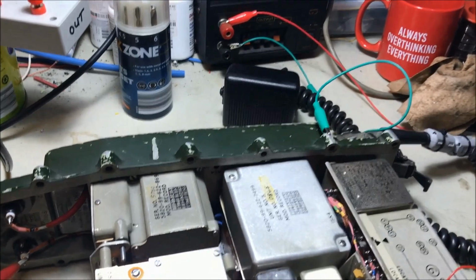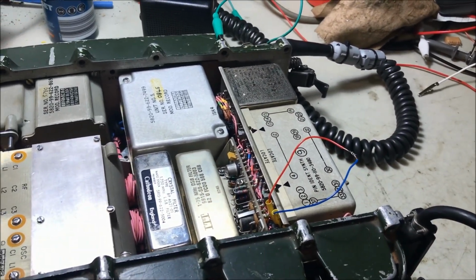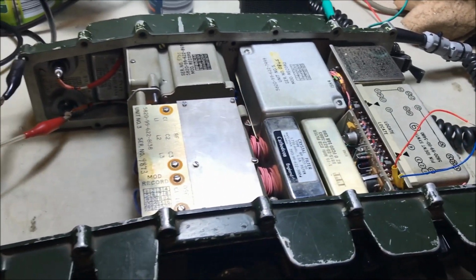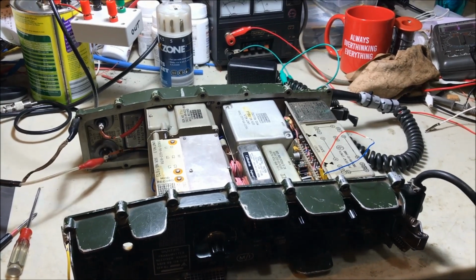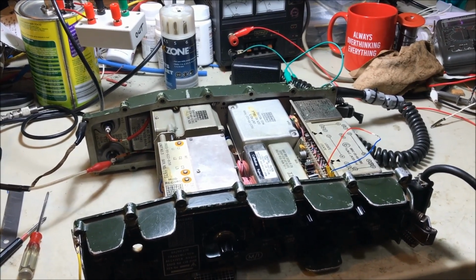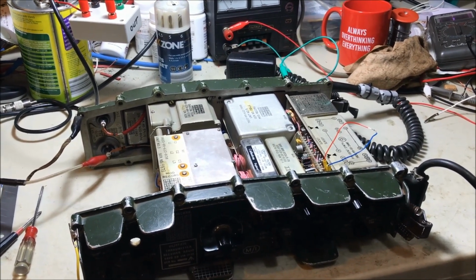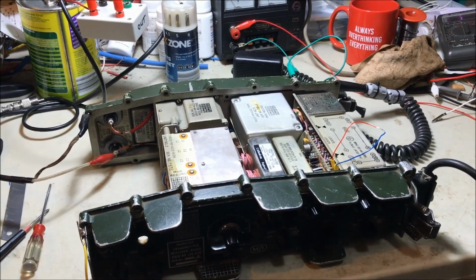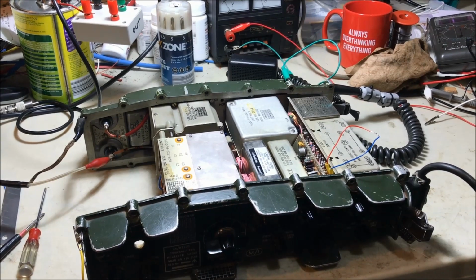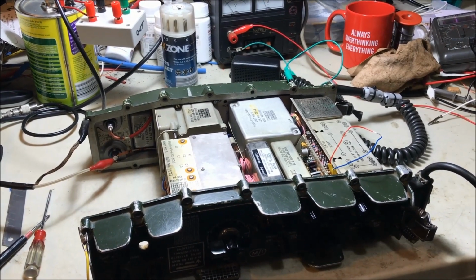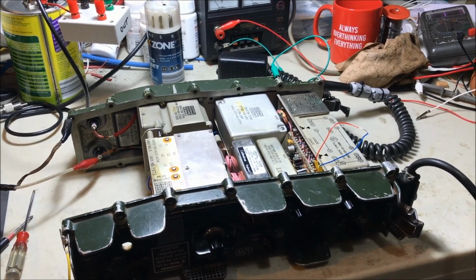What we're going to do is get the power supply happening, disconnect this wire here, and put the 15.28 volts into the blue wire. I'm going to turn it back on again and see what happens to our wobble. Now it'll be interesting to see whether it carries on or whether it stops. If it stops, it's the synthesizer, and if it carries on, it'll be the 3H board, which is the variable frequency oscillator. Almost time to diagnose our problem, so let's move on.